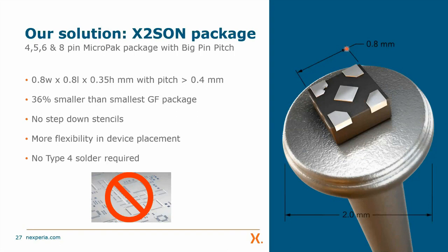In this case, it is only 0.8 millimeters across the side. However, because the leads now go diagonally across the center, I'm drawing the biggest distance. So my minimum pitch is closer to 0.4 millimeters instead. So I have a very, very small package, but I have a pitch bigger than that magic 0.4. So it's easy to manufacture in the device. So we got the best of both worlds. Small package, but big enough pitch that I don't need to use something special for it.